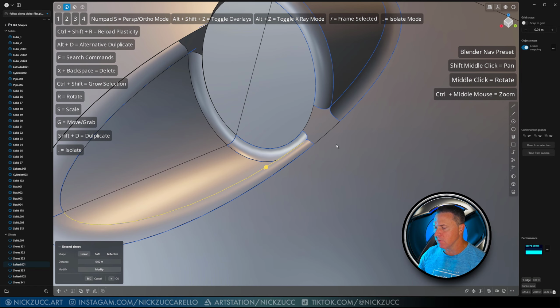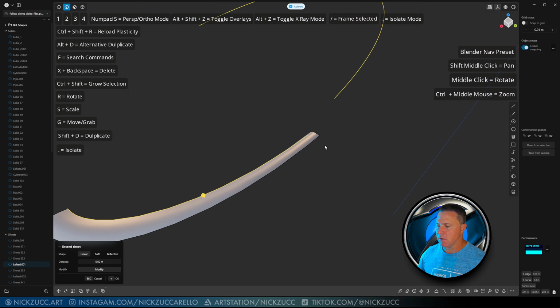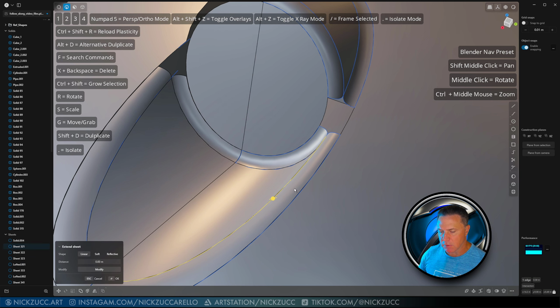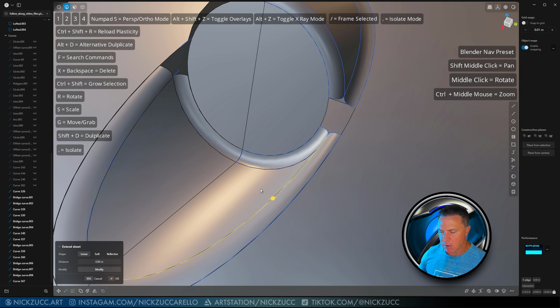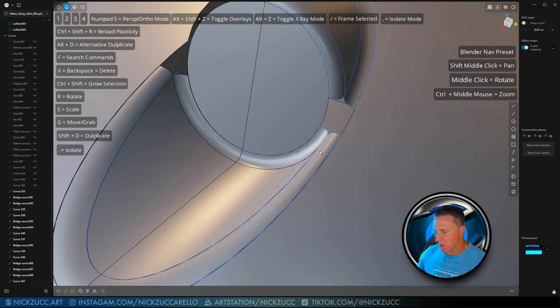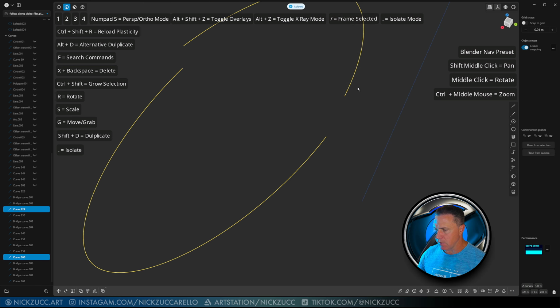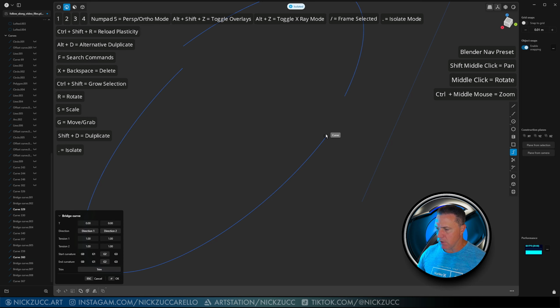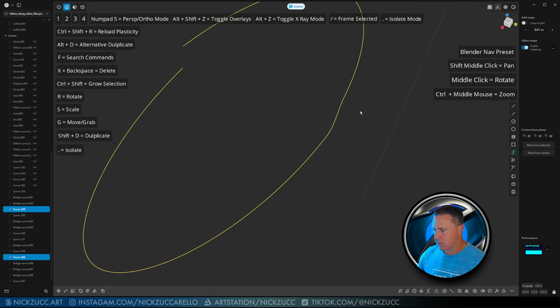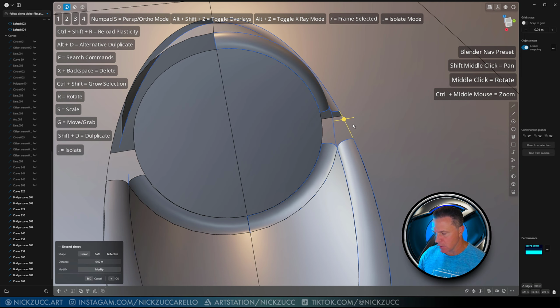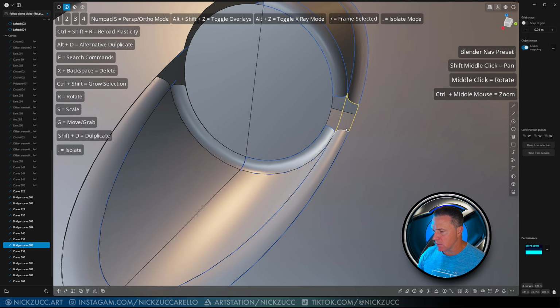I'm going to tap 2 for this curve, and this curve I'm just going to hit period to, oops, let's see, let's go select this curve right here and make sure I'm not selecting the sheet. Let's go select that whole thing. There we go. There's that curve, and this curve, tap period key. And again, Shift B to bridge, just like that. So now I've got this curve here. I need this and this. I'll hit Shift D to make a curve out of that. So I've got this curve, this, and this.